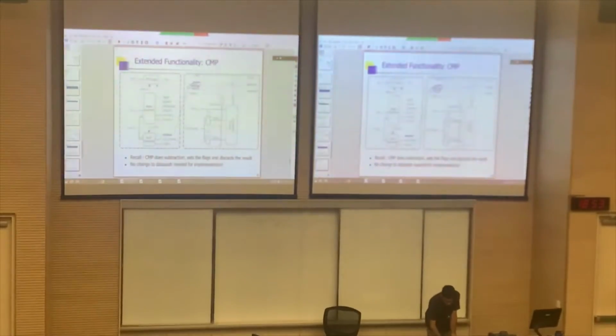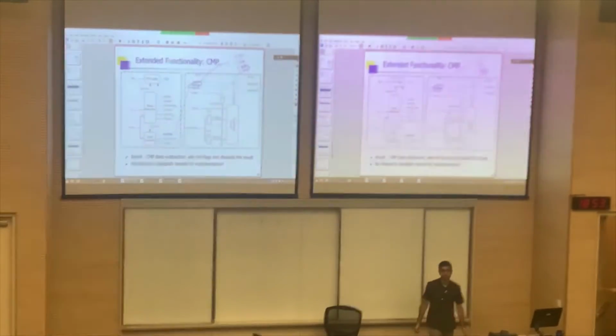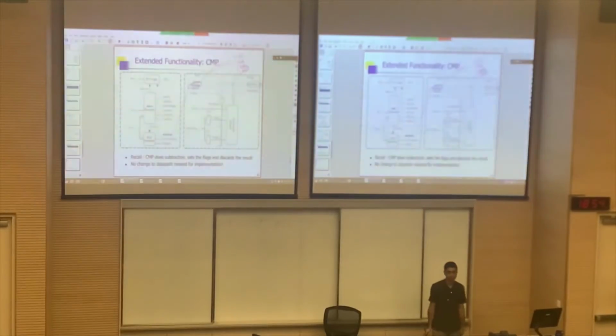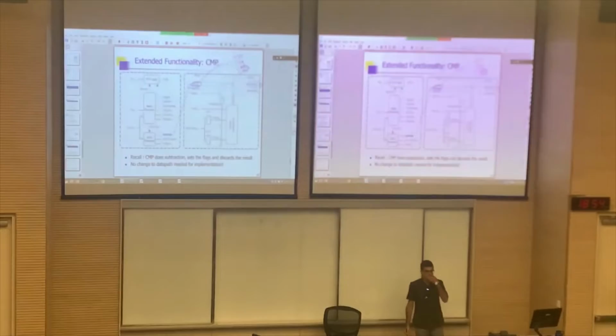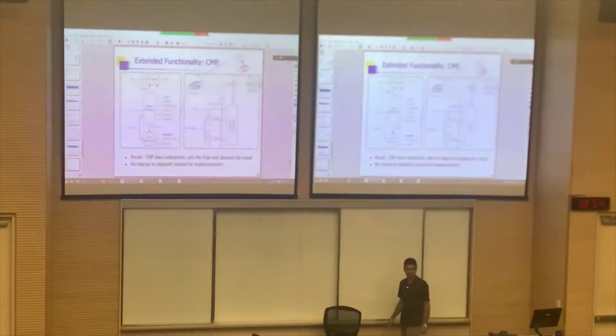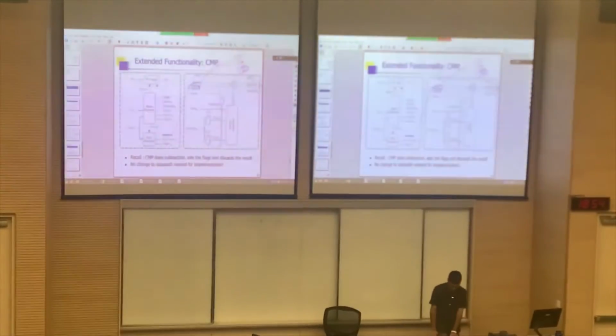So no write should be 1 for TST, TEQ, CMN and CMP. When no write is 1, reg write is 0. Some of you either did not generate no write correctly or did not connect it to this AND gate. So that's a mistake.